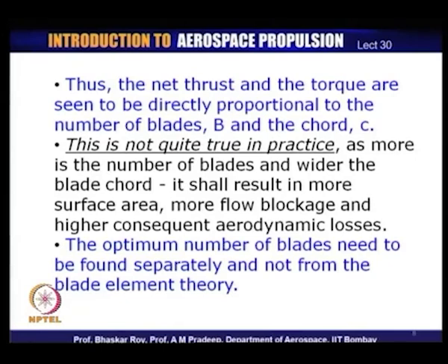In practice, that is not quite true. What happens is, if you increase the number of blades or the size of the blades by increasing the chord, it shall result in more surface area of the blades. If you have more blades around, it will create more flow blockage, and as a result, very high aerodynamic losses. So, the efficiency of the propeller blades would start falling.